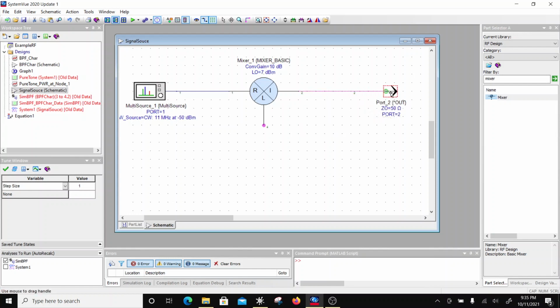This will directly go into the gain stage, which is going to be a PA or first or second gain stages, something like that. If you put gain over here, that will be more like your baseband gain, or in case of heterodyne it will be IF gain here, and in that case you can put filters around it. But once you have done the upconversion, you won't have filters, because the frequencies are close by, right?